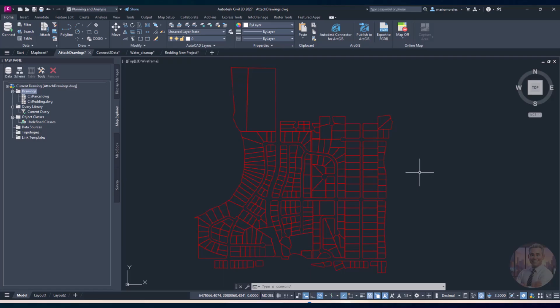And if you've ever gone into maybe your block list, because you're going to insert something, and you see a bunch of blocks that are like $AU6527 blah blah blah, those are usually from pastes. The software didn't understand what was on the clipboard. It grabbed it all, dropped it in maybe as a block, maybe you exploded it, and it just gave it some kind of cryptic name. Those will corrupt your drawings all the time. Okay, so watch out for those. Do not use copy and paste. You can use W block, right blocking things, or you can use some of the methods I've shown you today. But really avoid those copy and pastes. Those are just bad news when it comes to working with intelligent objects, especially BIM objects.